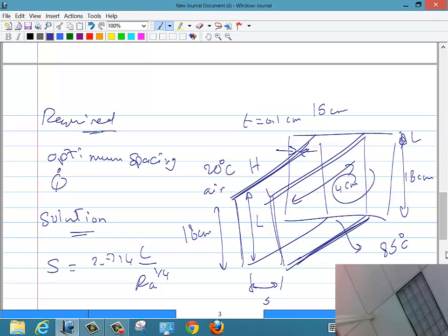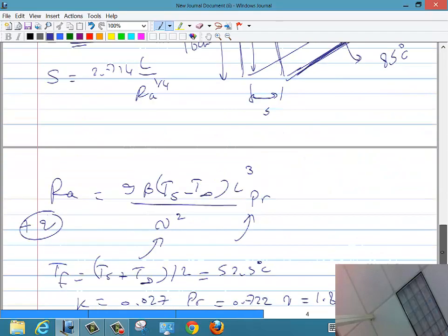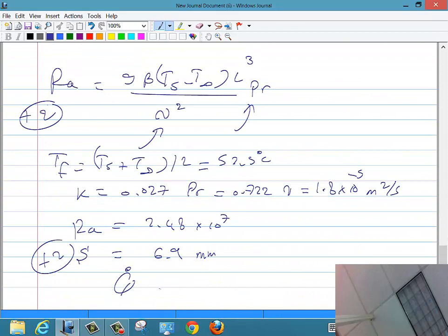This equation is probably worth 30% in every problem, convection-wise. You know, just write that Q is HA delta T. H times the surface area times the delta T, the surface minus the fluid. All right? So Brandon is correct. So Q dot is HA times Ts minus T infinity. So now we have to figure the H and we have to figure the area.